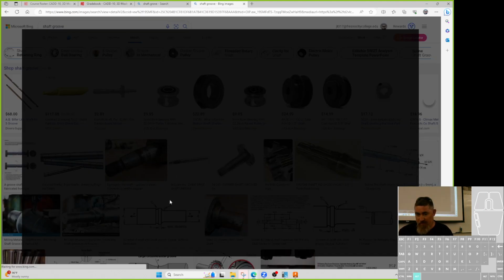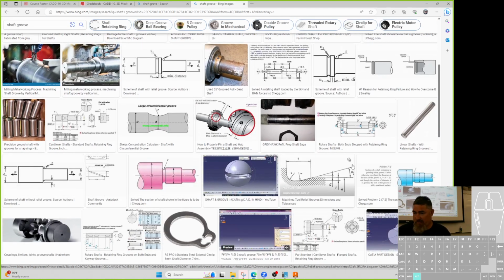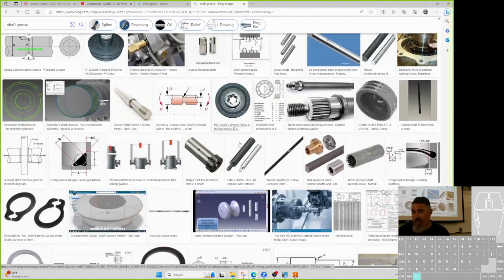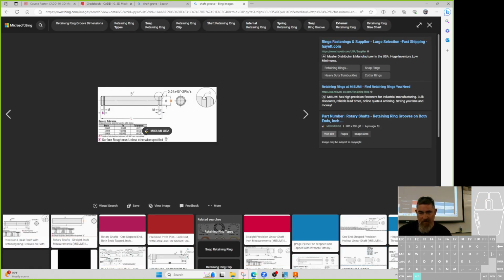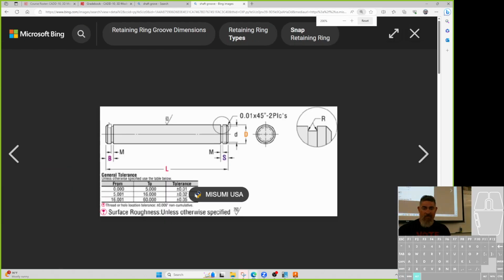So here's some other things. So rounded grooves, do it like this, right? Draw a circle, revolve it around. Things like that. You also see reliefs like that. Here was kind of an example. So right here, there's a groove, but it's got square corners in it. See that? It's got square corners in that groove. Should I revolve that? Is that a good candidate for revolve? It could be. And I always used to use Revolve for this until last year. So that's one I could revolve.